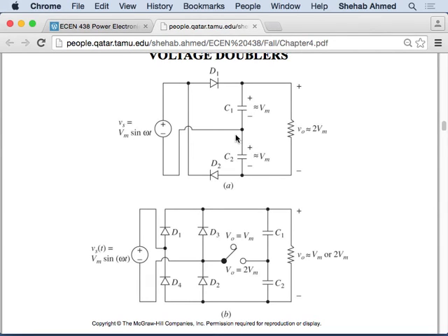So now the supply will come in and charge this capacitor. And again, like my previous cases, if I've properly chosen my size of the bucket, then the capacitor will maintain the voltage to a large extent. But what's going to happen beyond the peak value of the sine wave? Same thing that we had before. During the first half cycle, beyond the peak value, this capacitor voltage is maintained, and I have a small current being drawn here.